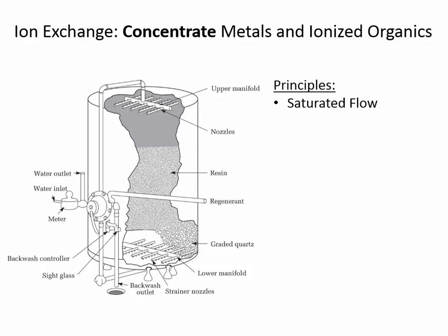In an ion exchange, what it is, is a special resin, as it's called, and you could think of it maybe as beads. There's some sort of beads in there that have the ability to attract whatever it is we're trying to concentrate. This is used for water softening, but it can also be used for the removal of hazardous metals. Usually when we're doing water softening, we're just getting rid of hardness ions like magnesium, iron, manganese, and those aren't necessarily toxic to us, but there are things that we'd need to remove like chrome, zinc, copper. The concentrations could be high and dangerous.